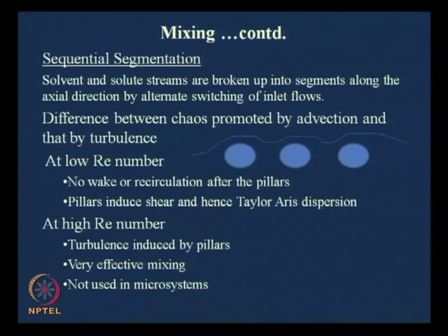For example, in membrane separation processes, if you have studied this as part of mass transfer, one established method is putting some pillars on the membrane, so that when you induce a cross flow over the membrane surface, those pillars act as turbulence generators. Around those pillars there would be turbulence, with cross eddies forming, and that would help mixing on the membrane surface, because what you have to ensure is that the formation of a boundary layer is minimized.